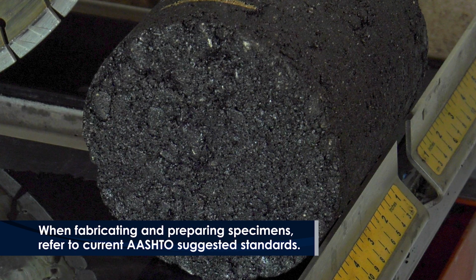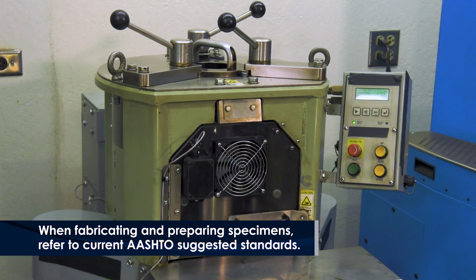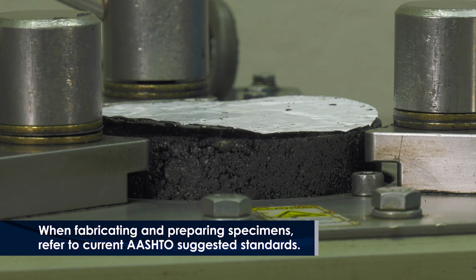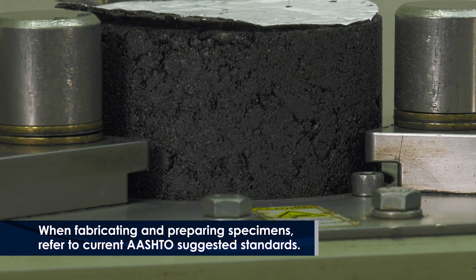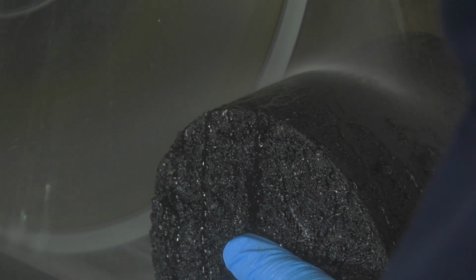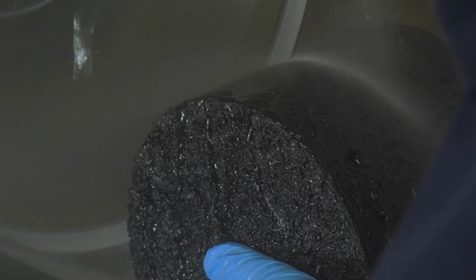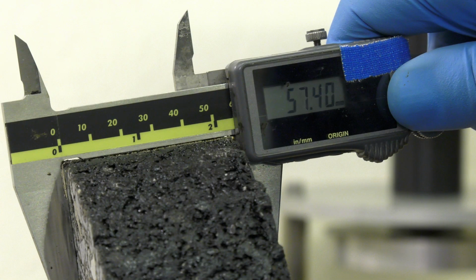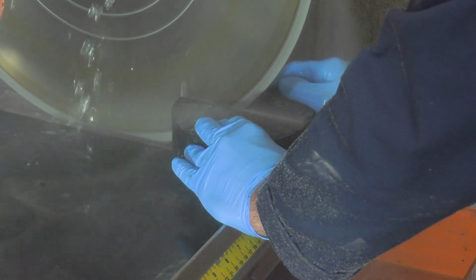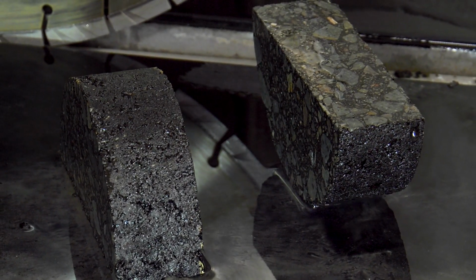Fabricate at least 3 SGC samples with a diameter of 150 mm by 120 mm thick using a superpave gyratory compactor. Target air voids to 7% plus or minus 0.5% according to ASTM D6925. To prepare the semicircular shaped test specimens, cut a 150 mm by 120 mm SGC sample into 2 identical 57 mm thick circular discs from the middle of the SGC sample. Cut the disc into 2 identical semi-discs along its central axis. The height or radius of the 2 samples should be within 1 mm of each other.